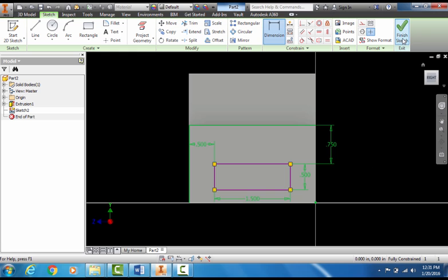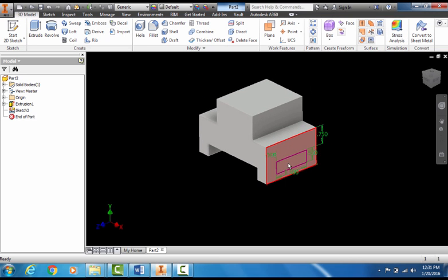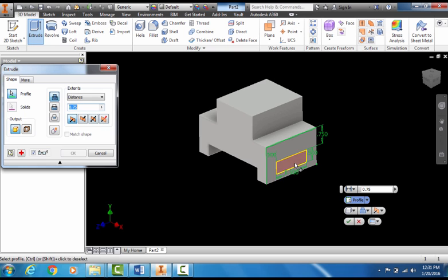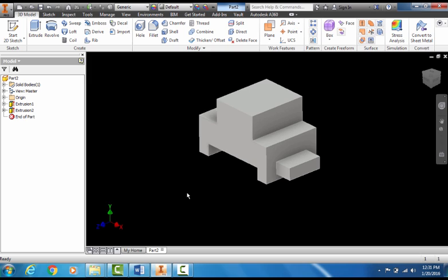Okay, now let's go ahead and finish our sketch. We're going to make this thing extrude here. So we're going to extrude it, make it stick out 0.75 inches. Right there. You got to click on it and then hit OK. And there we go. We have our first part using the additive method, where we are combining two or more shapes or forms here because it is the most efficient method to create this, because we were adding material.